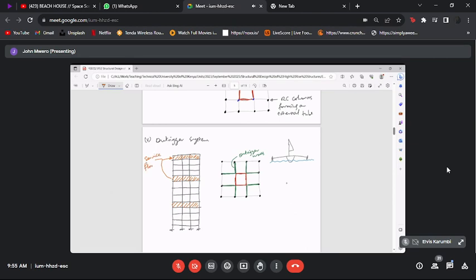I'll explain what that is. When you design a tall building, say beyond 25 stories, you start having a need to have some floors that are just for services like water pumps, water tanks, compressors for ventilation and things like that at different intervals, because it might be difficult and inefficient to pump water, say up a 60-story or 100-story building.